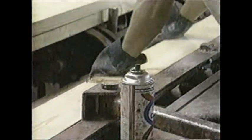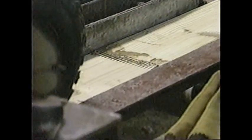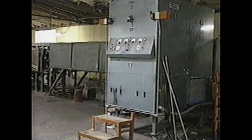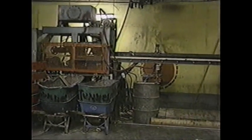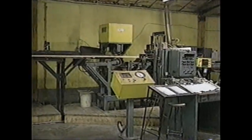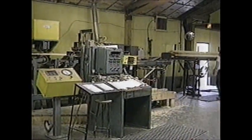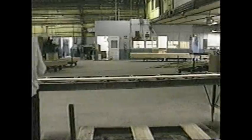The finger jointed stock is joined by hand. The nature of the joint makes accurate assembly very easy. After joining, the continuous length of stock passes through a radio frequency glue dryer. Emerging from the tunnel, the stock is cut to lengths dictated by production requirements. The cut-off saw is computer controlled. The stock is then surfaced 2 sides to bring the stock to a standard thickness and to remove glue extrusions in preparation for the laminating process.